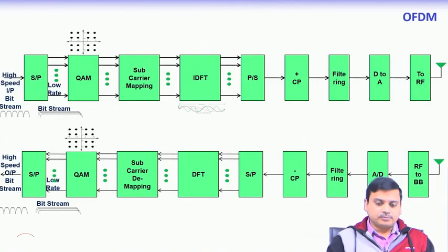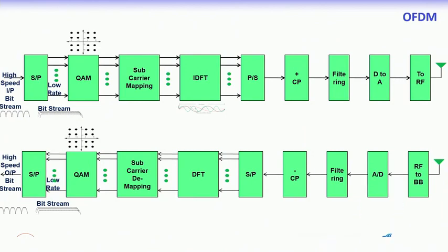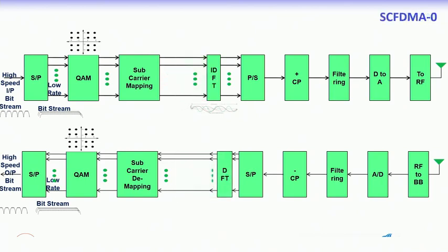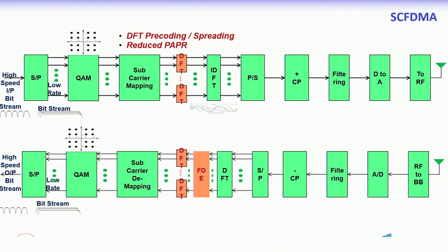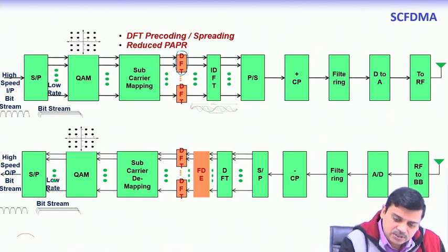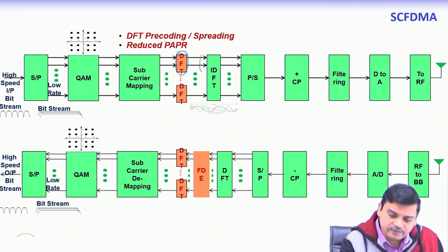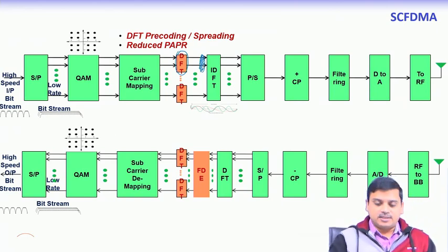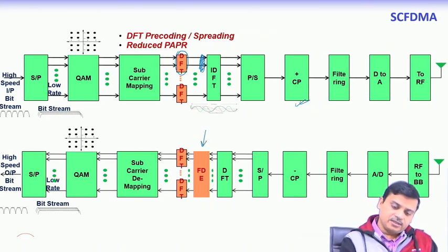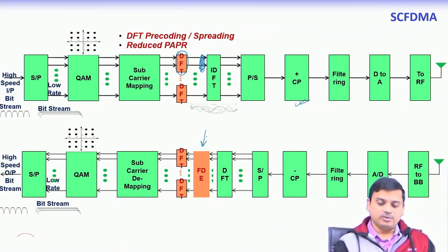generation system as well. We have explained thoroughly in the previous lecture that the typical OFDM structure, as you can see in this slide, can be used for further modification. With slight changes, it can result in very significant things. What we said is that this DFT spreading is done over a set of subcarriers, and this causes the individual subcarriers to appear as if they are coagulated, giving the notion of single carrierness. At the receiver side, because we are using a cyclic prefix, we can avoid ISI and get the frequency domain equalization benefit. This we have also discussed.